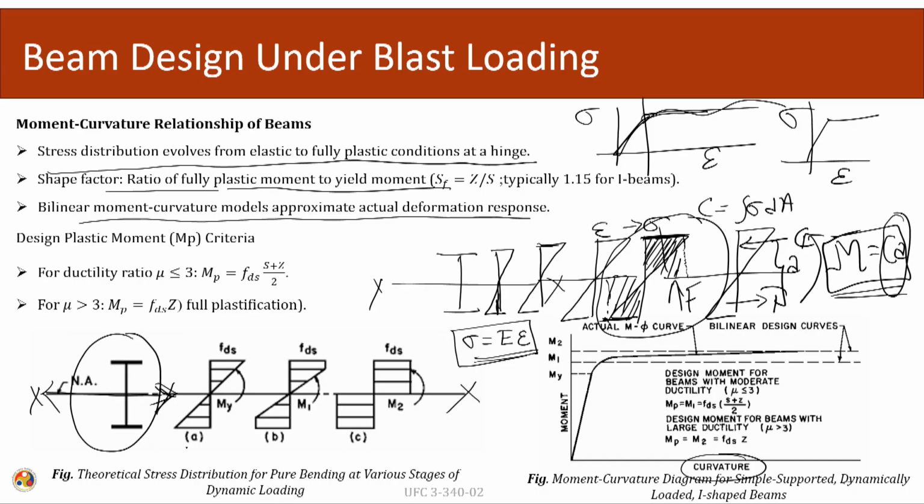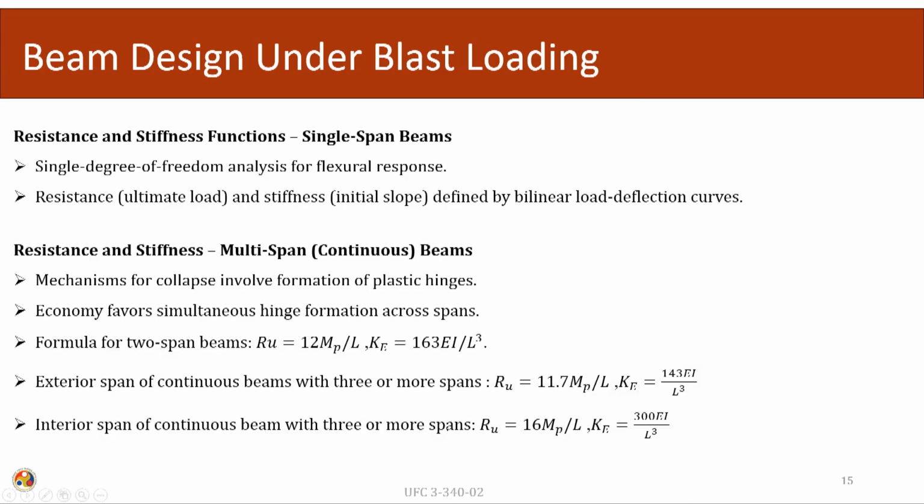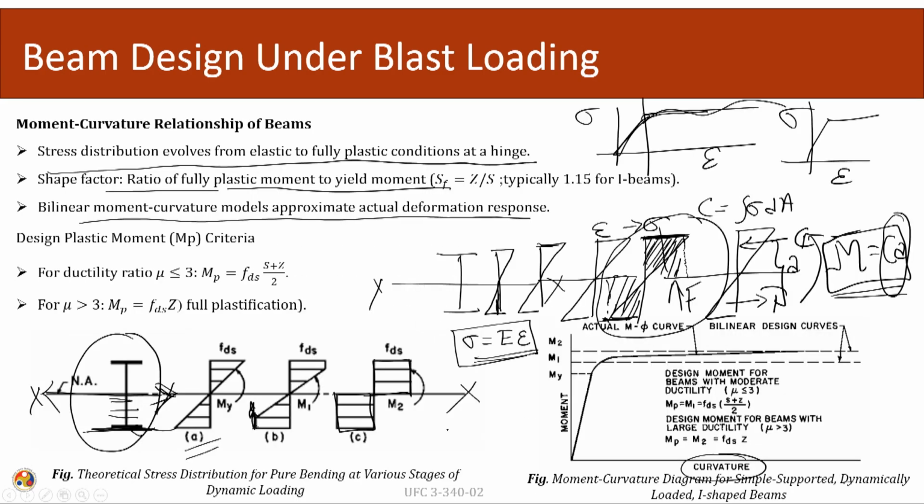So, this is the elastic region. After that, the elastic limit has been reached and this is being propagated into the other fibers. In the outermost fiber the elastic range has been reached, and now this is being reached in the inner fiber zone also. Once this is complete, we say that the fully plastic region has formed and a plastic hinge has been formed in my system.